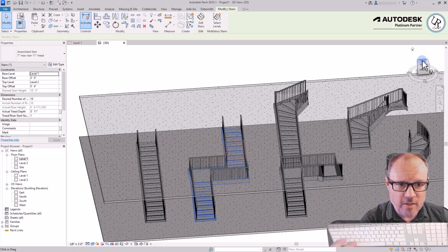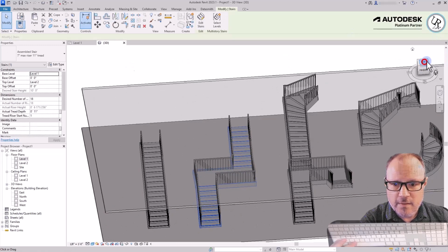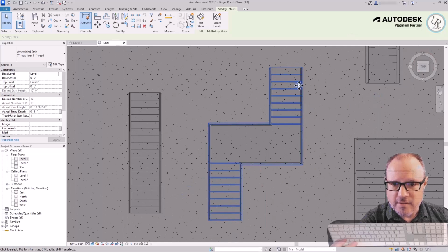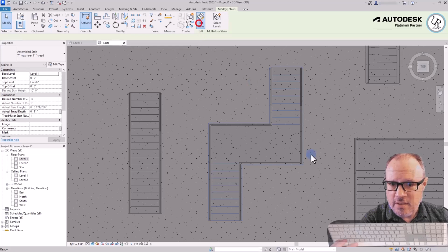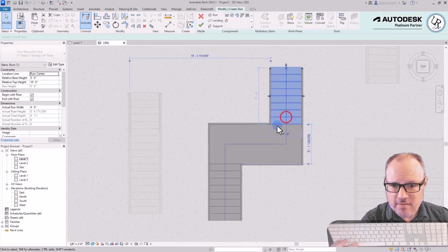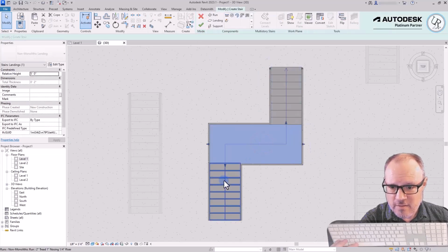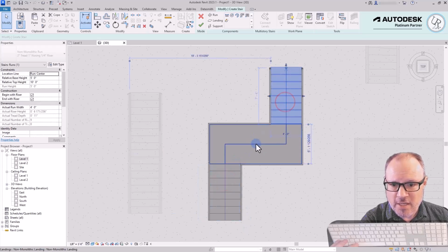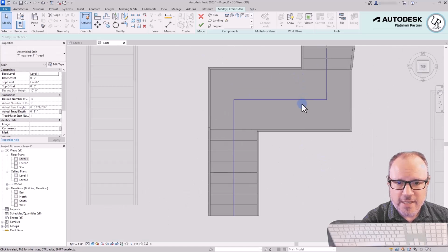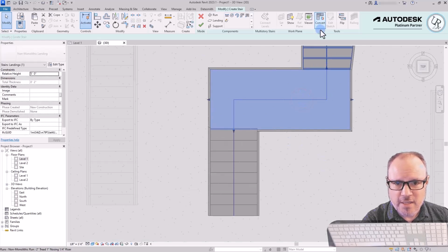Taking a look at this stair first, I can select that stair and look at the Modify tab. I have an Edit Stair option. Edit that and it turns the design of the stair on, and I have the ability to select each run and length of landing. On the landing, select the landing condition. Again, you have to convert that separately to a sketched outline.